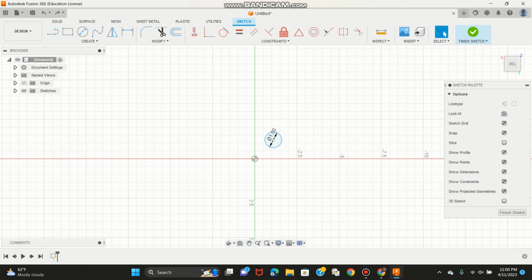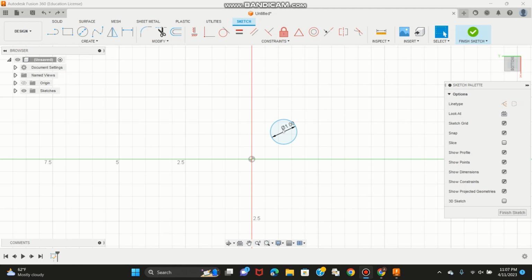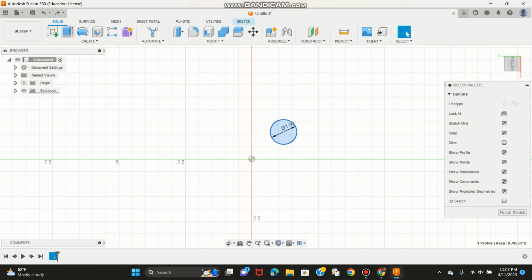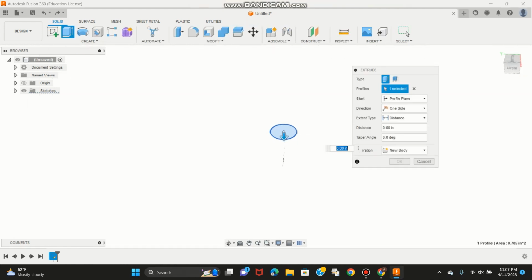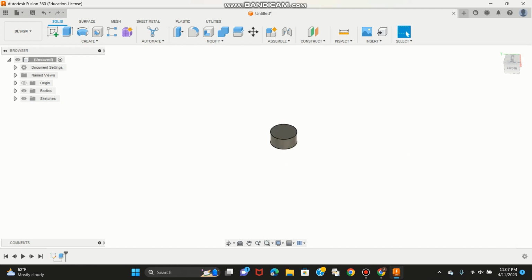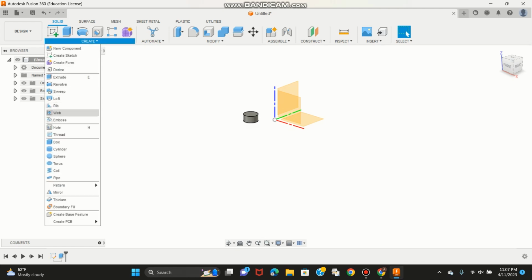And we'll be moving on to 3D now. So now as we go on to the 3D aspect of patterning, you can see that we right now have a 2D sketch, right? So let's make that a 3D model by extruding it. So hit that circle, extrude, and let's go up, let's say 5 inches. And let's go back to our home view so we can actually see where we are in the work plane, hit the origin. Okay. So now what we can do in the 3D model part of it is hit the create button. So it's in the same place.